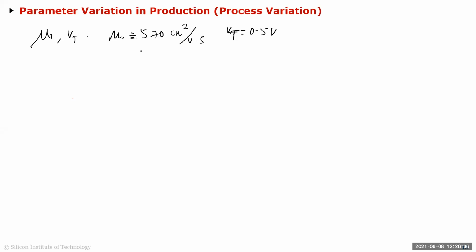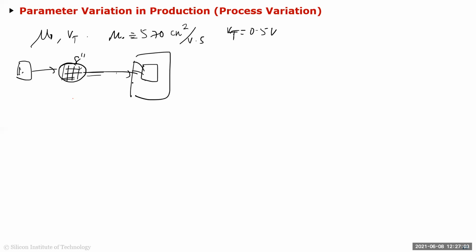And what do you mean by process? If you remember, in our first class, I gave you the whole design flow. So you do a layout and all that, and you send it to the fabrication house. They take this circular 8-inch wafer, and they process your chip, and then they cut and slice and dice it, and then you get these chips, which you package and bond out, and you get these nice packages, which you put on your breadboard and start testing. Now the thing is that each time it comes out of the fab.